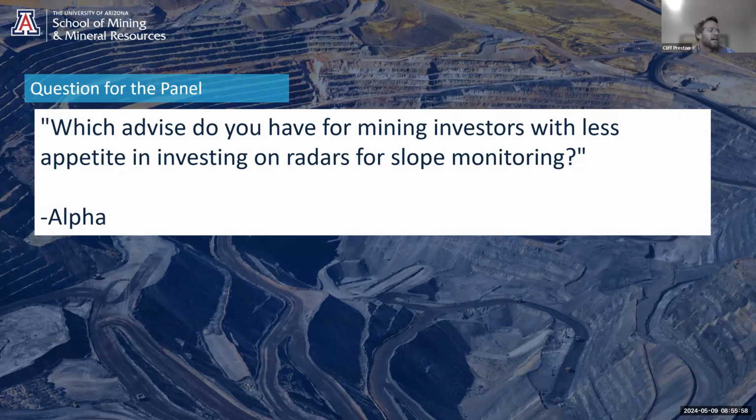Yeah, and just to add, like what Paolo and Albert saying, it really comes down to the design of the slope of the pit and the slope monitoring program that you have, because you don't need radars everywhere. You could design a very shallow pit that's going to be very inefficient for you from the investor side, and it will be unlikely that you would need maybe a slope monitoring radar in that case.